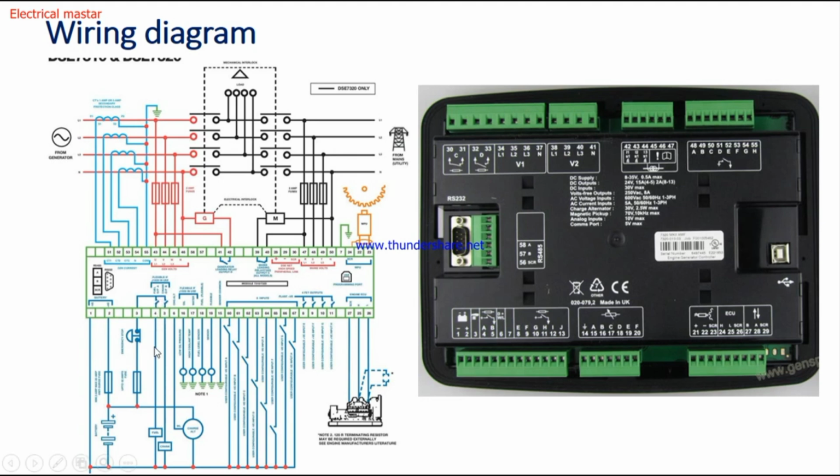The 4th wiring is going to connect to the fuel solenoid, and for the 5th terminal, we need to take one wire and connect it to the starter solenoid system. So the generator starter solenoid, we need to connect here, the fifth terminal.